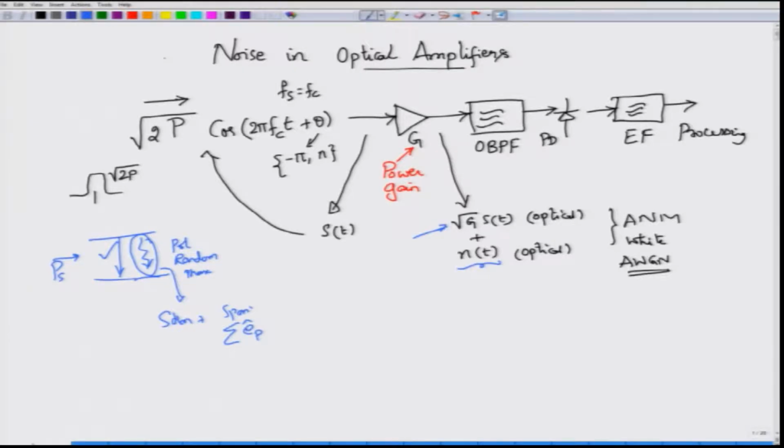It would also fluctuate in frequency because, although the center frequency would be Fc, the amplifier itself has a wide bandwidth, so the frequency is completely fluctuating or changing. In addition to that, there is a different noise as well. So, you might imagine that the overall spontaneously emitted field could be written something like this, where Fi stands for different frequencies within the bandwidth and theta i stands for the random phase that goes with that.